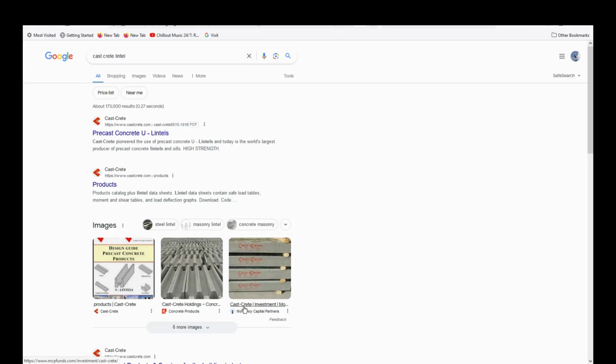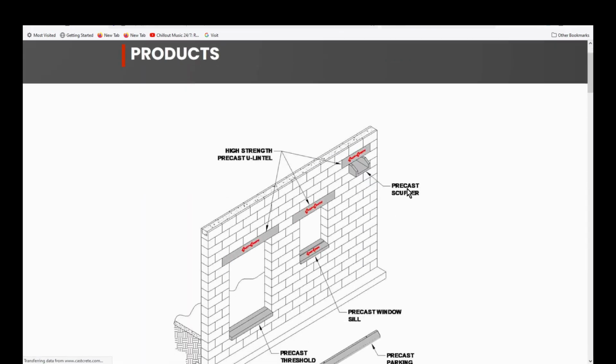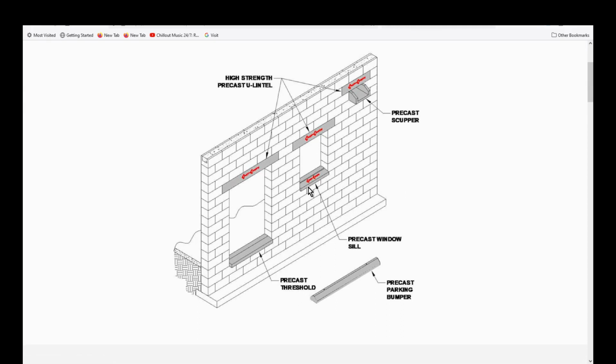So long story short, with normal masonry construction, here's an excellent graphic. They have lintel, it's a lintel, so it's like a concrete beam that's pre-made. The masons will put it in place. If it gets really heavy, they crane them in, but usually they'll have a couple guys lift it up and they'll put it in place. So the key things really are these lintel headers.